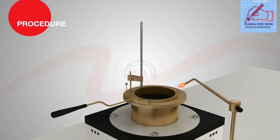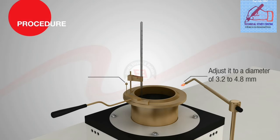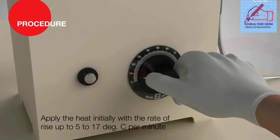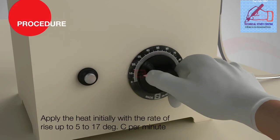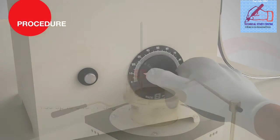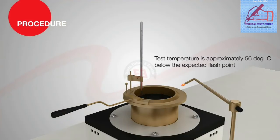Light the test flame and adjust it to a diameter of 3.2 to 4.8 mm to the size of comparison bead. On the regulator, apply the heat initially with the rate of rise up to 5 degrees Celsius to 17 degrees Celsius per minute. When test temperature is approximately 56 degrees Celsius below the expected flash point,